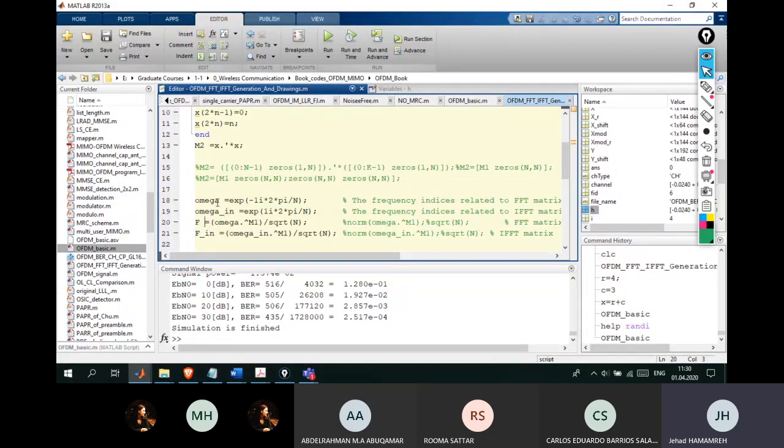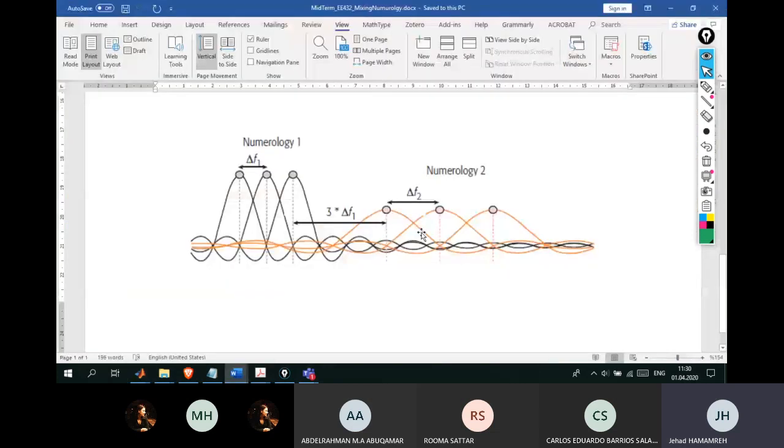So I want to see these figures. I want to see these plots, the sines and cosines, the carriers that carry my data, how to play with them, how to change their spacing, how to put them adjacent to each other by math. And so my question is basically here, if you noticed, the idea that one of you might think of: one might say, okay, they are interfering with each other, and I can see that there is little interference coming to this point, to this point, to this point from these subcarriers. So one solution might be to calculate this amount of interference and try to subtract it, or introduce something auxiliary to your system that, when you put it with these waveforms, can subtract the interference, or you change the shape of this waveform so that it makes sure there is no interference to the adjacent one.